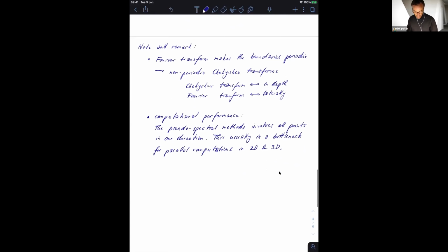And then the final point is about the grid points per wavelength. So when we use finite difference schemes, it depends on the order of the stencil, but like a rule of thumb usually is that you need between 5 to 10 grid points per wavelength that you want to simulate.